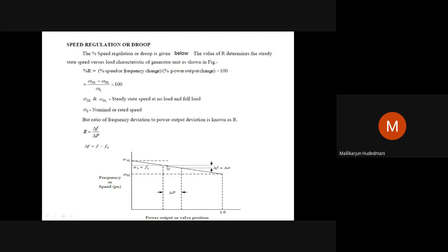And this deviation in frequency is due to the shift in load, that is delta P. A small demand increase is called delta P. Then the slope of this curve can be easily plotted as delta F over delta P. A small slope, delta F over delta P, if I take, that becomes the regulation of this particular curve. In that proportion, it is going to work. No other way, you just see. So for a particular delta P, you take this delta P to the LHS and bring the R downward. So for the delta P requirement, the particular P it can apply can be taken from this calculation.